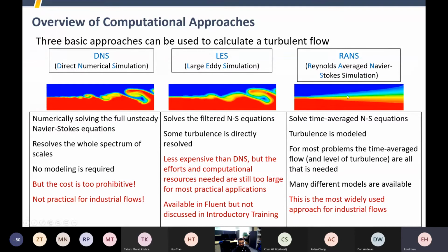Whereas in this case, in order to get an accurate resolution, we need maybe 2 or 3 elements across the same thickness. And in a boundary layer, that's where we're having some really important effects of turbulence that can cause separation. And so having a really good RANS model that can make assumptions about the turbulent structures is really helpful.